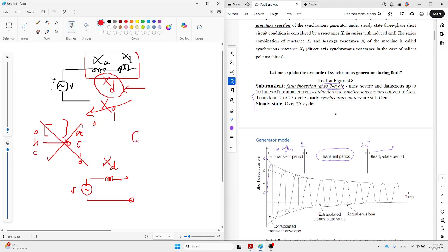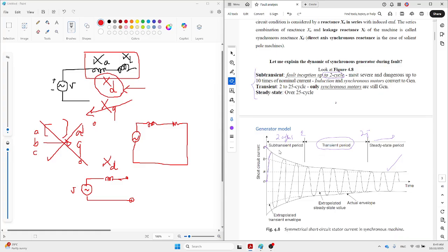If you can remember, in circuit and electronics, you usually model a circuit using L and R, and then you have two responses: transient response and steady state response. Can you remember that one? So during the fault, the power system is analyzed based on the same condition. One is the steady state response, which comes from this part, and the other is the transient and subtransient, which is related to the switching and the DC effect. The meaning of switching for us here is the fault.